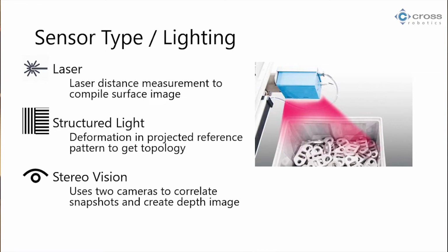Structured light, similar concept, but almost entirely different. So we'll just say it's a different technology. Structured light means, on one hand, you have a projector, you have a known pattern, right? And you shine it onto a surface. And then with a camera, you look at all the deformations in your pattern. I forgot to advance this. So that's a laser scan going on, right?